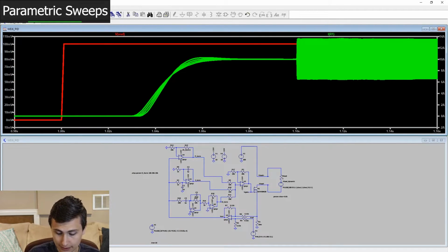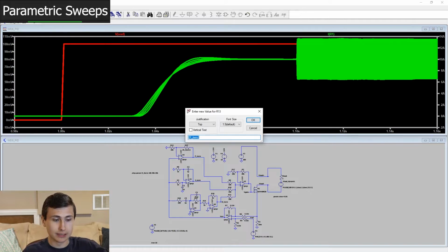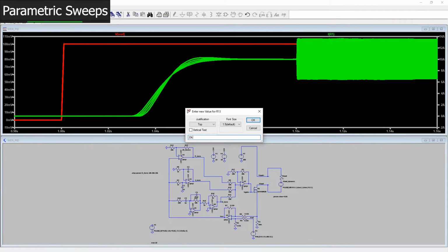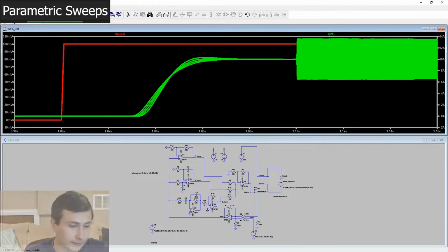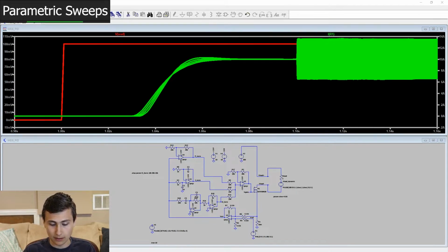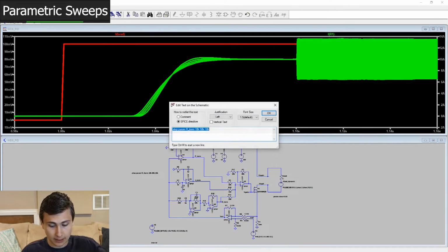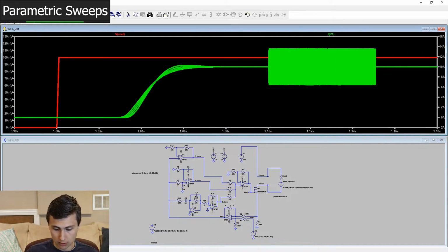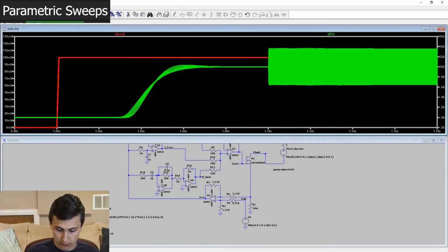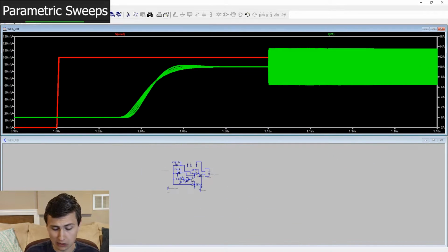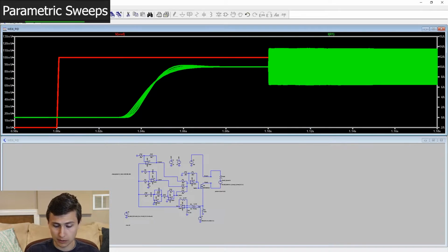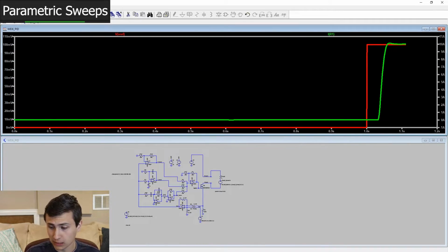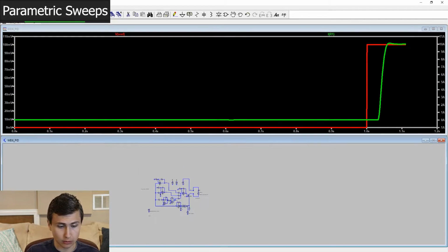Yeah, let's keep this relatively tame. Let's keep it at 20K. That is a gain of 3. So, with our gain of 3 fixed, our D term kind of locked in where we like it, our I term in a pretty good way, let's run the simulation again. Should just have a single run.